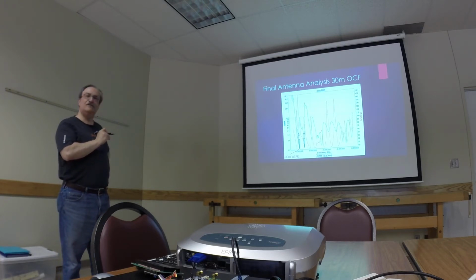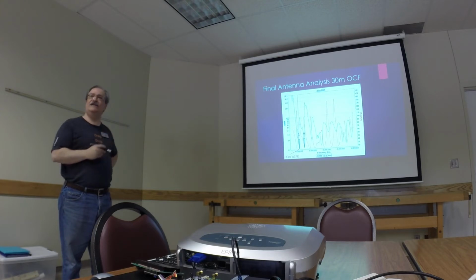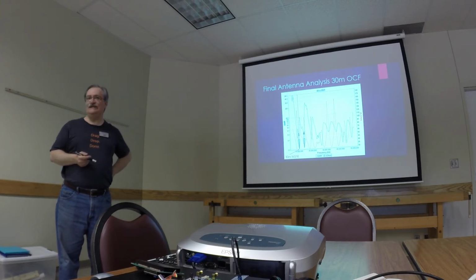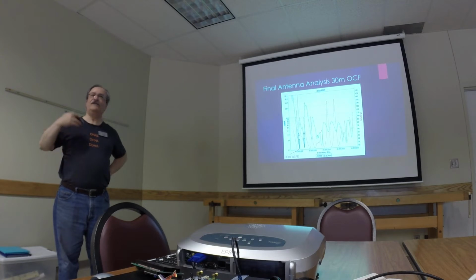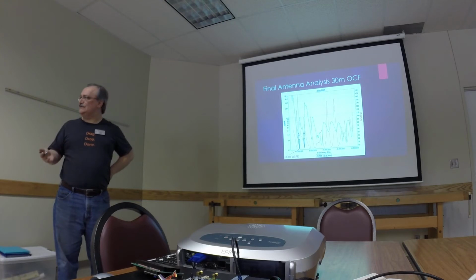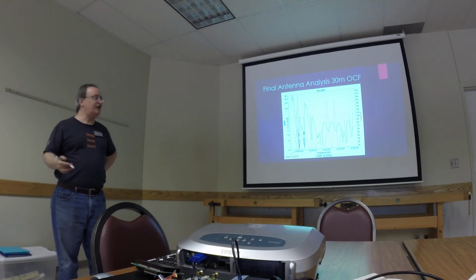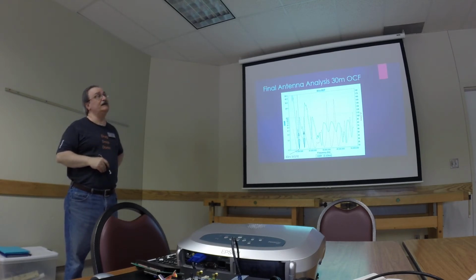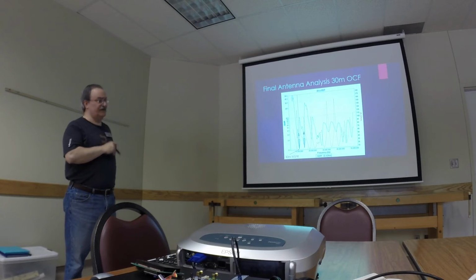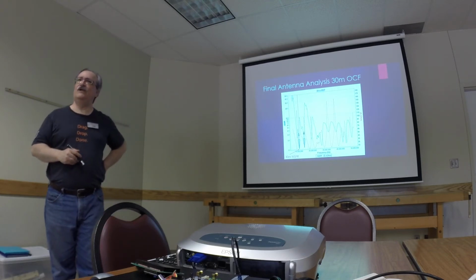But as a 5/8 wave antenna, it's resonant at 14.2 megahertz. Now that's kind of unusual, it's kind of unexpected. You won't find in any of the books that say an off-center fed antenna will have 5/8 wave or 1.5 wavelength points or anything like that. Books are books, they cover the general stuff more than the real world, they cover the theory. But interestingly enough, that came out to about a, well, this is 1.1 to 1, and this one I think was about 1.15 to 1.